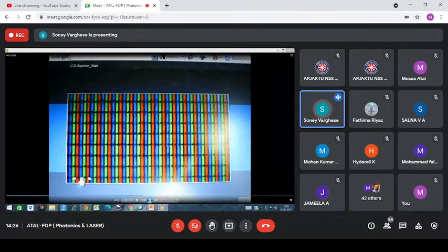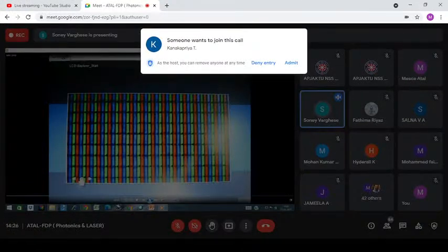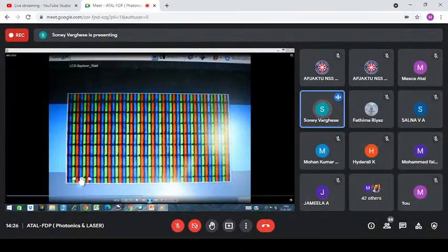So you can start seeing the pixels. As you know, the pixels are the picture elements, which contain the primary colors, red, green, and blue. Each pixel contains three subpixels, red, green, and blue, as primary colors. And we have individual control over each pixel. We can play with each color by just changing the voltage applied to the transistor on the subpixel, right? The field effect transistor is a switch which is used to switch each subpixel. So each pixel will have a transistor.